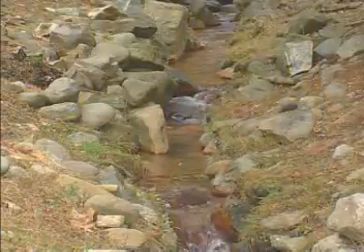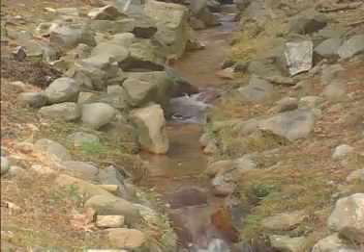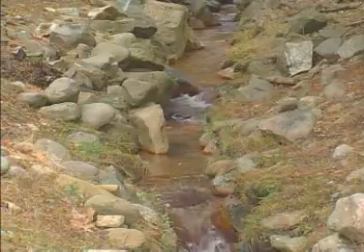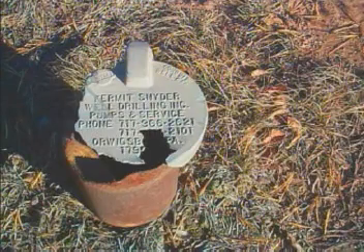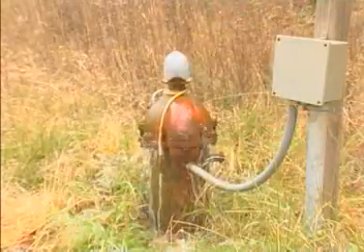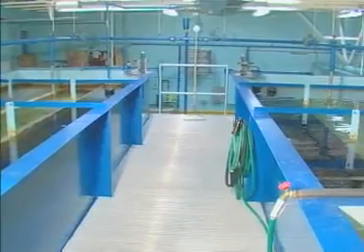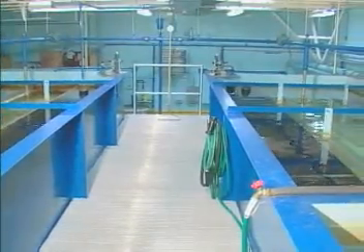Some groundwater may also be considered under the direct influence of surface water. An example of how this might occur is that an abandoned well with the casing at or below ground level could channel surface runoff directly to an aquifer that also serves as the source for a nearby active well. Groundwater in this category may require treatment similar to a surface water source.